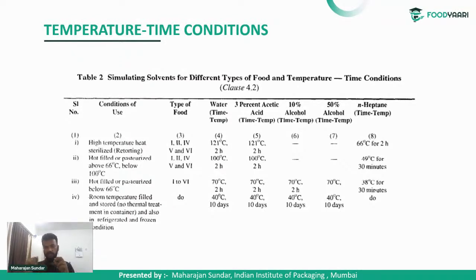And then finally, we have to measure the remains of extraction, so that final weight minus initial weight gives the amount of concentrate. Usually for flexible plastics, the amount of migration should be under 10 milligram per decimeter square.